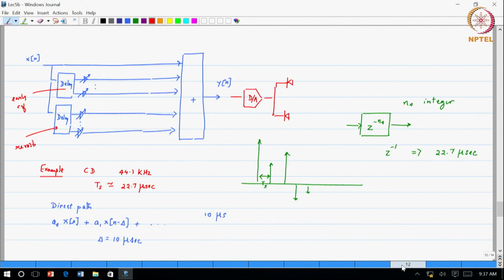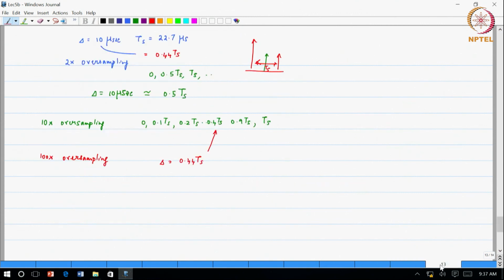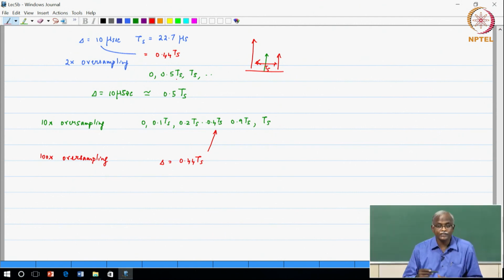It says that I want to recreate the concert hall effect, which means that I must recreate it with several signals of several delays which I need to combine. That depends on the acoustical properties and not necessarily on my sampling period. And if I want to achieve something that is very close to what I want to implement in the ideal case, then multi-rate signal processing is a very useful tool, which we can exploit and take several very good advantages from.